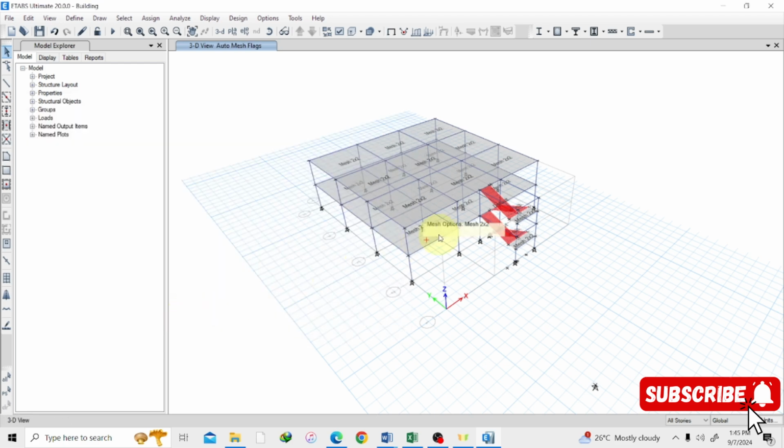And okay, so now our mesh has been applied. We've assigned our mesh to this slab. So now our slab is able to distribute loads and act realistically. So our mesh is now 2 by 2.